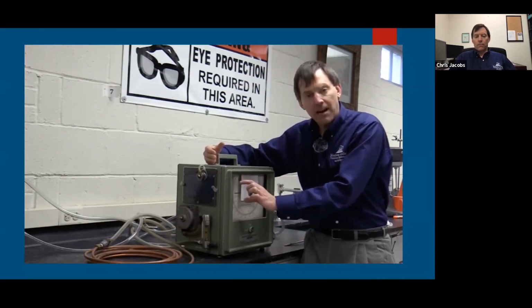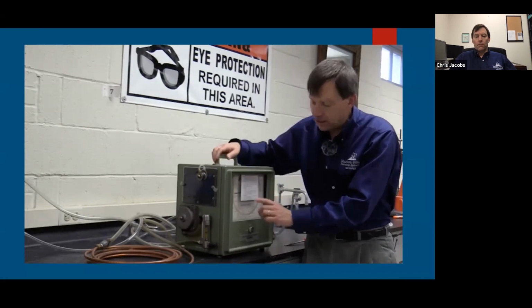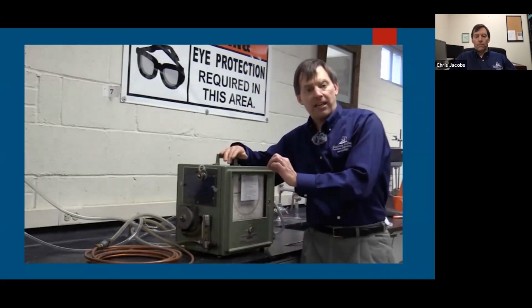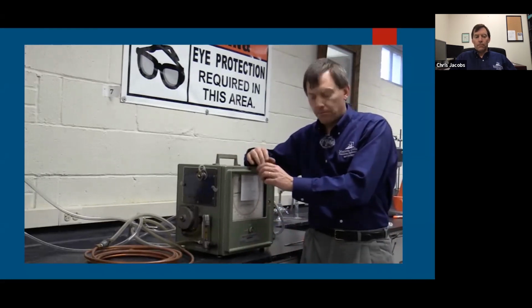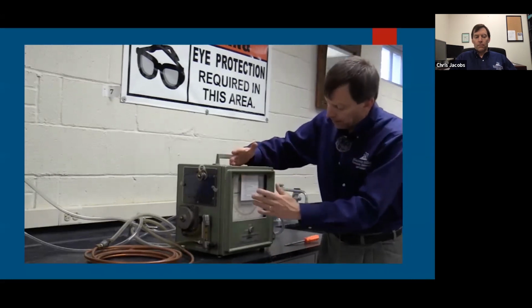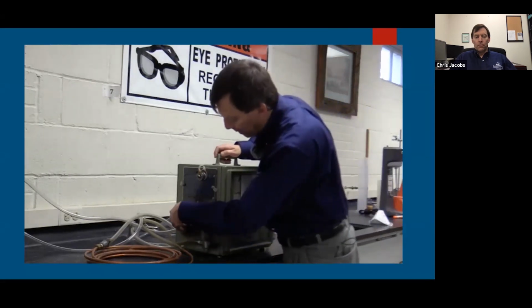And then you want it to stabilize. Once it stops moving and stabilizes, you know what the specific gravity is. So I will read that right now. It appears to be stable. It's just about 0.6. So now we know the specific gravity of this gas sample is 0.6. Once we've measured the gas sample, we will turn the selector valve back to 0.